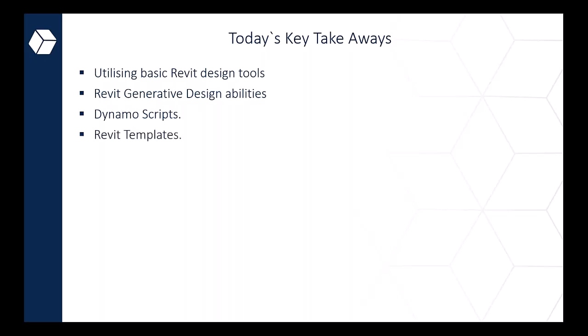And then we looked at Revit templates and the importance of those templates, why you should set up your template as a basis before you start off your project in a conceptual design phase, because having all of those elements or families or project browser settings or view template settings in that Revit template can save you a lot of time each time you have to create a new project.